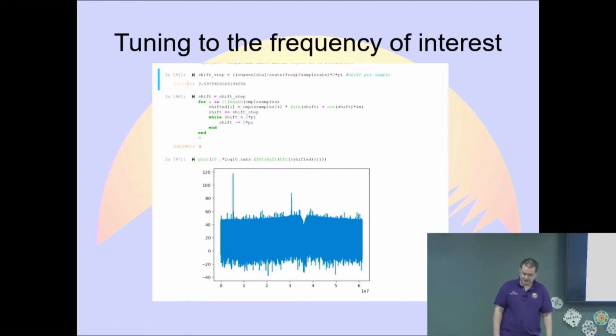And so we generate a sine wave. This probably doesn't show on the screen very well, but we do a pointwise multiply, convert to dB, and convert to the frequency domain. And you see that our signal that was on the right has now moved to the middle.